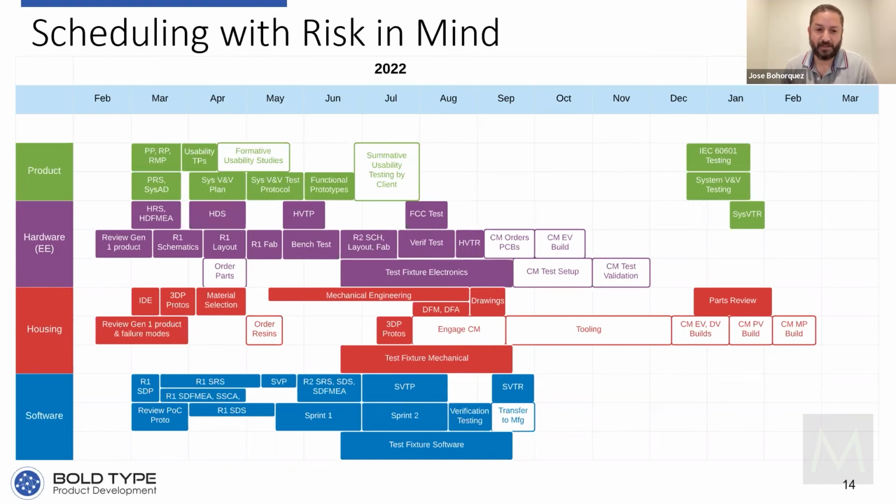And then I show a couple of other things that commonly don't show up in risk analyses, but as a sign of the times, if you look down in the purple area where there's a white box that says order parts, right? Under normal circumstances, you might not be ordering your electronic parts until later, as you're getting ready to manufacture. Today, we tell our clients, once we have a preliminary schematic and we know what most of the electronic components are, you might choose to buy early.